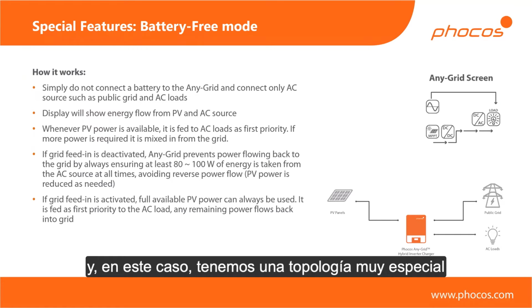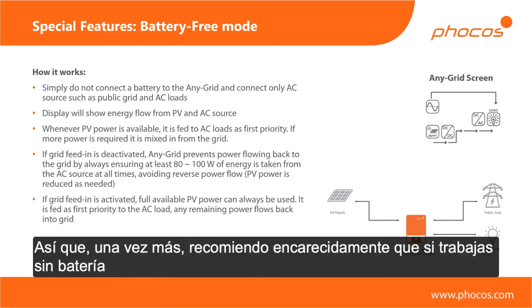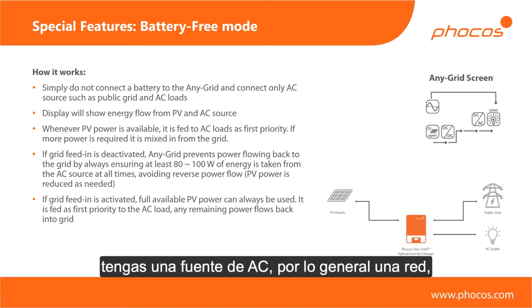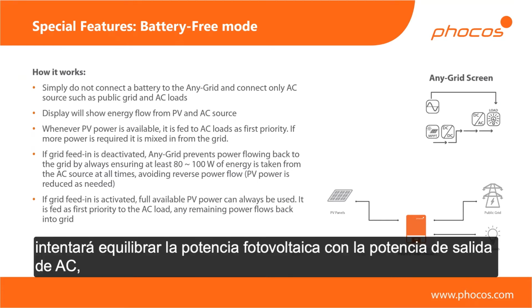And in this case, we have a very special topology for this unit, which actually allows functioning without a battery. So again, I very strongly recommend that if you work without a battery, you do have an AC source, so typically a grid. But theoretically, even if you don't, what will happen is it will try to balance the PV power against the AC output power.